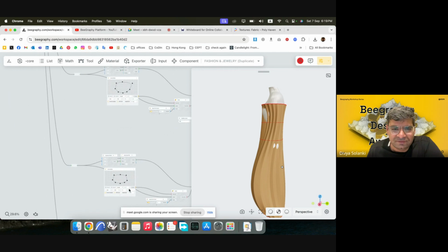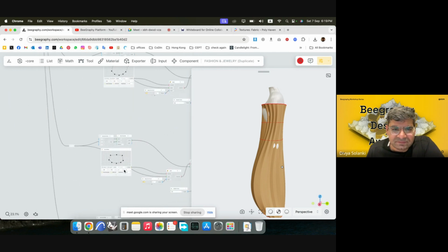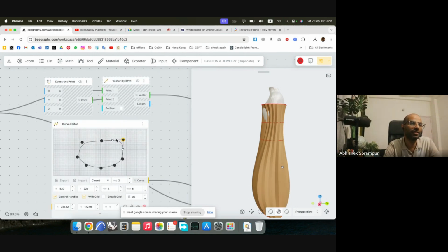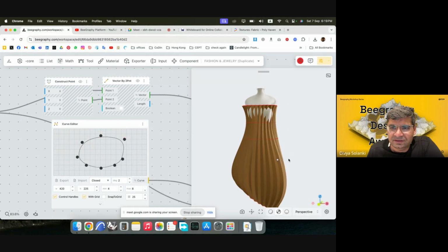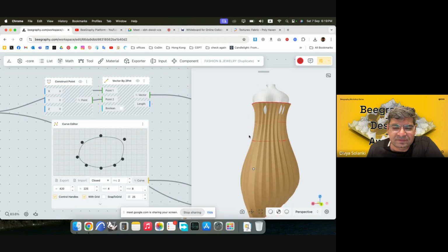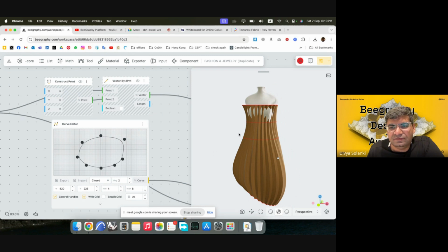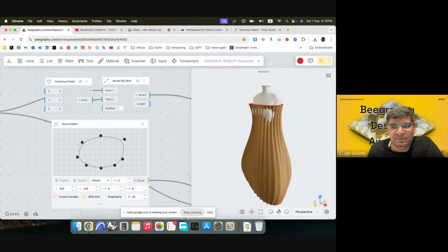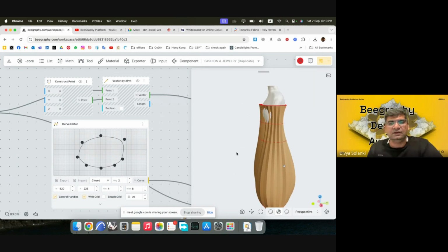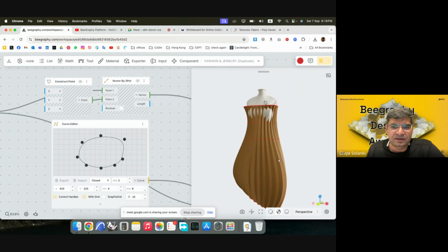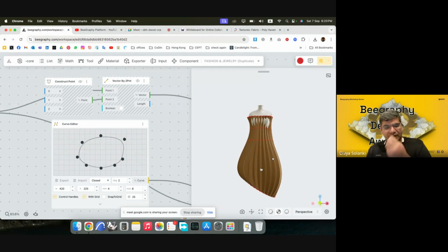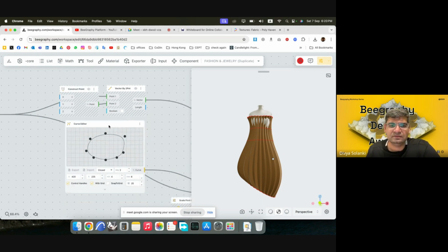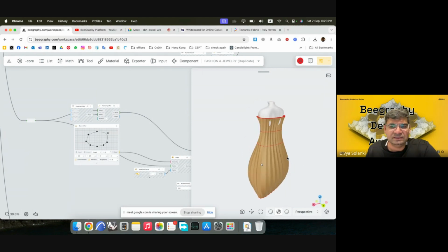So this is like the third one. If I modify just this part, then you can see it will modify accordingly. You can increase the number of these lofts to as many as possible based on wherever the geometry is changing. So I can maybe introduce one more here, and then it could be closer to the mannequin that we have. It will make it easier for us to design. All of this is parametric, so it can easily be modified.